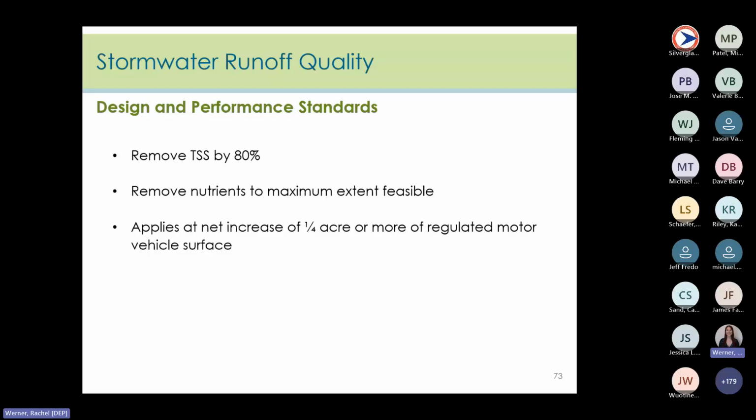So let's talk about TSS for a second, just so everyone understands what it physically is. It's a measure of the concentration of solid particles that are suspended in water, as opposed to dissolved. This includes things like sand, silt, and clay, organic matter such as leaves, and just general trash from the site. It's the things that make the water look turbid or cloudy.